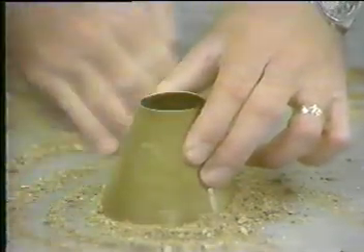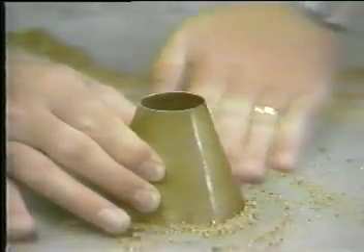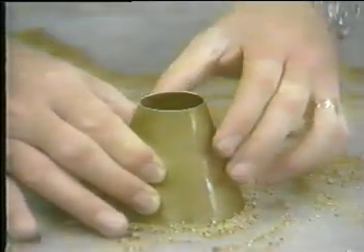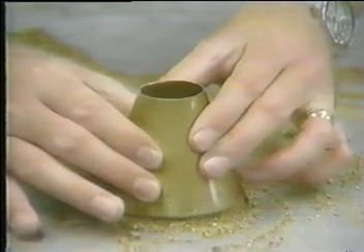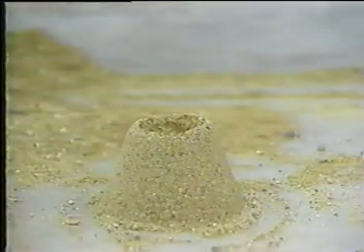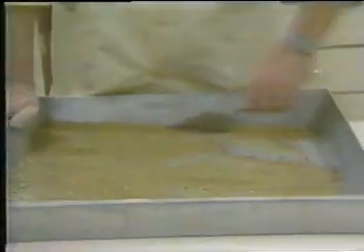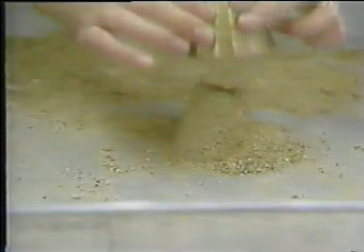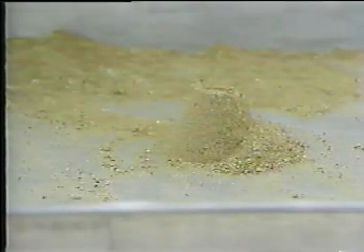Remove loose sand from the base and lift the mold vertically. If surface moisture is still present, the fine aggregate will stay in its molded shape. If the fine aggregate slumps slightly, this shows that it has reached a surface dry condition. The first cone test should indicate some surface water on the specimen. Continue drying with constant stirring and test at frequent intervals until the test shows that the specimen has reached a surface dry condition.